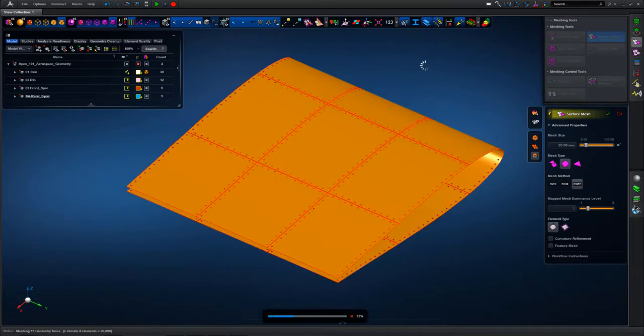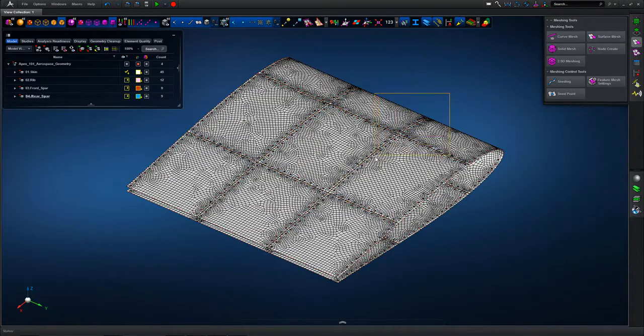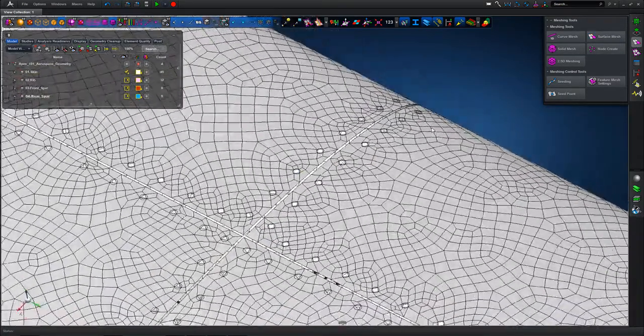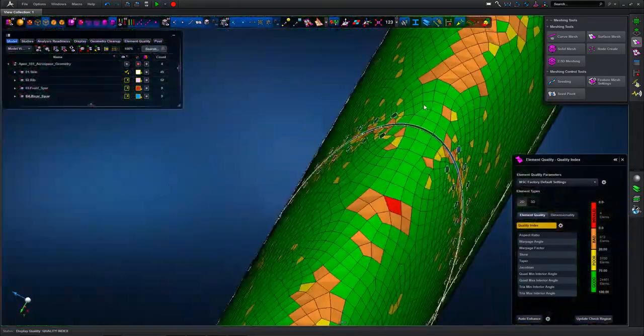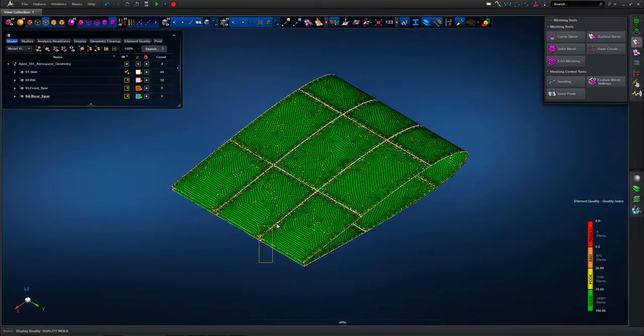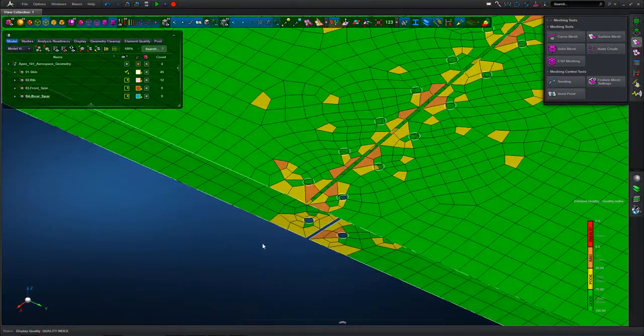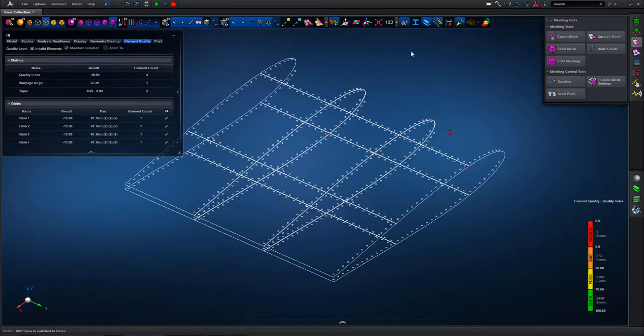So again, repeating this exercise, but you saw there we had to use pretty fine mesh. We could transition away from the fastener region, but we just used a single element edge length for the full model definition. In this particular example, we're using a much coarser element edge length or mesh size, and we can see that we've got some pretty poorly shaped elements around the holes, given that they're still captured within the geometry.